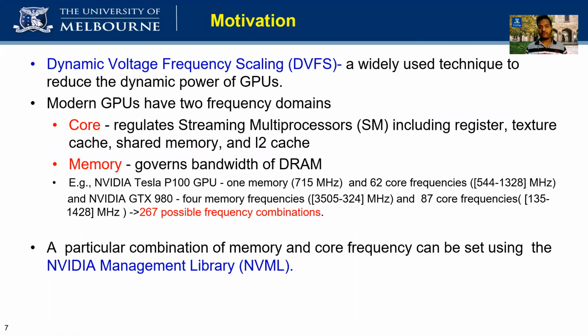There have been different methods to address the power consumption of GPUs with different abstraction layers and resource management techniques. However, at the lowest abstraction layer, power consumption can be addressed with two components. One is static power, another is dynamic power. Static power mainly deals with the leakage in the circuit, which can be addressed with a better circuit design, as well as low power management or sleep state management of processors.